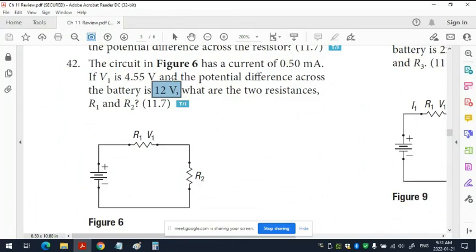I added the what? The voltage of group 1, the voltage of group 2, the voltage of group 3, the voltage of group 4. What did we get when we added them within rounding error? We get 120.1, which is very close to what? What does that mean? 120 given by the battery is split over everything. Do you see what I mean? Everything somehow has to add up to the battery.